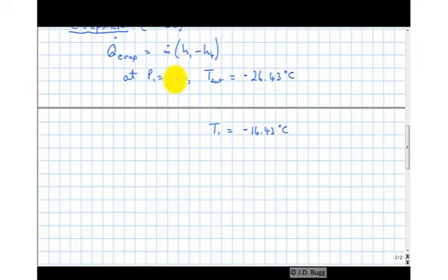So those are our two properties, pressure and temperature, and of course we know we're in the superheated region. So we go to the superheated table for R134a and we find this gives us an h1 of 239.45 kilojoules per kilogram. It's never a bad idea, while we're in the table anyway getting enthalpy, to get the entropy as well.